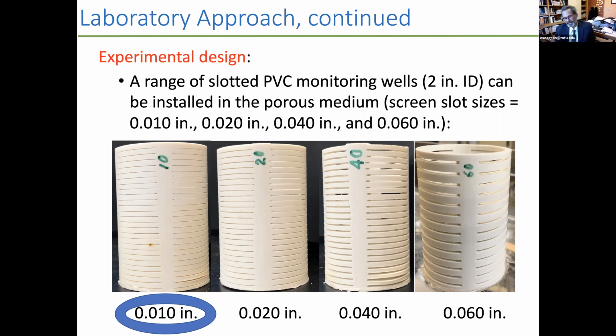Yeah. The other reason we got down is because I was thinking about one way that it might be done is to repurpose a monitoring well. So this would be not an atypical monitoring well construction. So what's going to happen if I put a reactive material down a monitoring well that I'm repurposing? So that was another driver here. But it would be interesting to look at some really high permeability screens, and we should then be able to get those kind of maximum plume widths. Yeah.